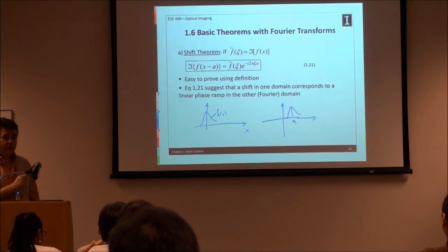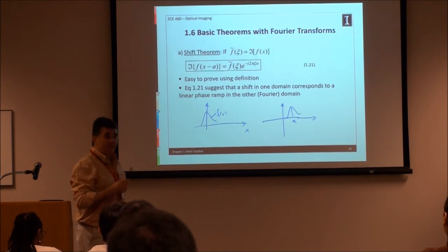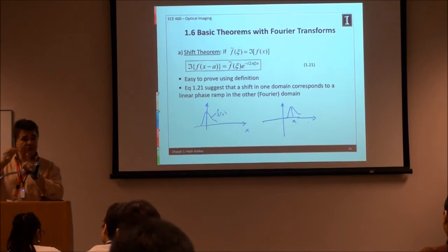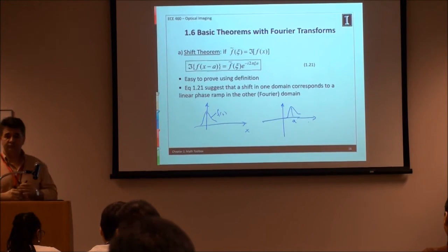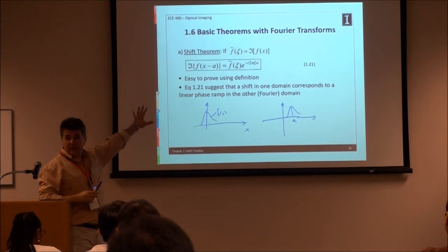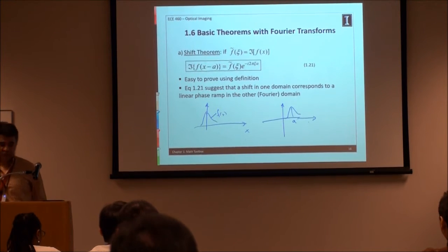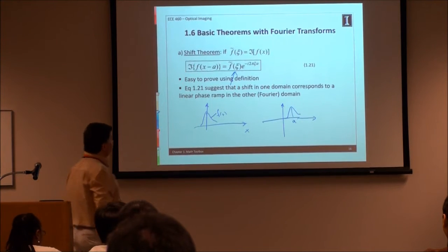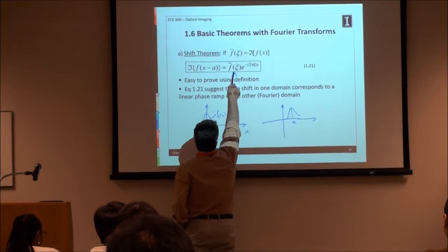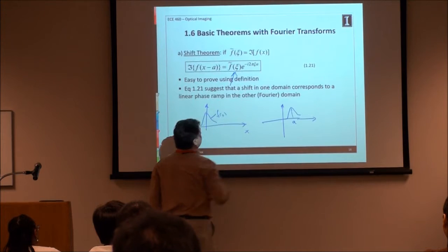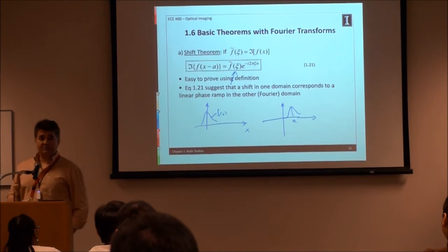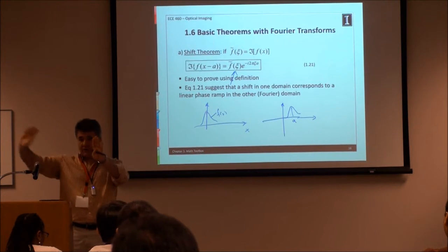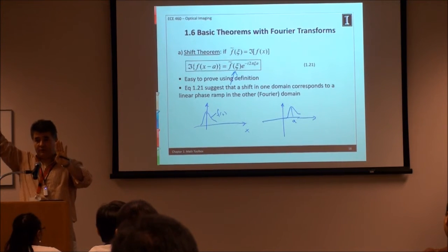And again, I don't want you to think we're doing math here or undergraduate math. Think of those delta functions that reconstruct your general signal. There is a shift in there, right? It's important to find out the Fourier transform of a shifted function. So what is that? Well, it's right here. It's the Fourier transform of the unshifted function times a complex exponential. In other words, the Fourier transform of the shifted function times some modulation, right?